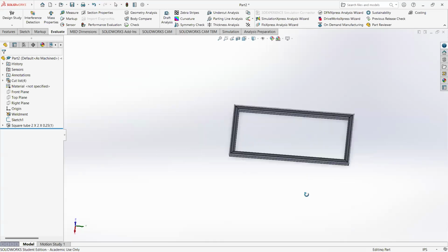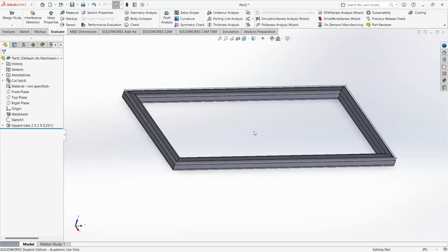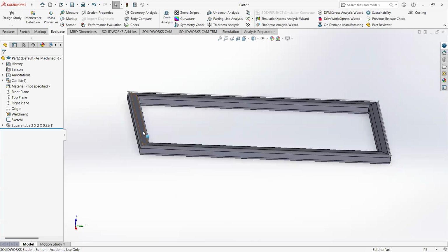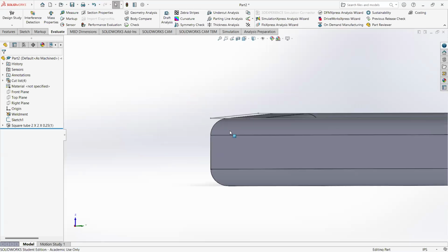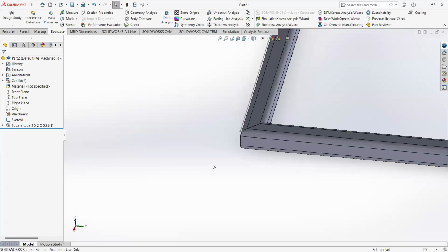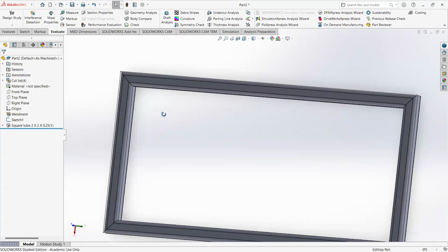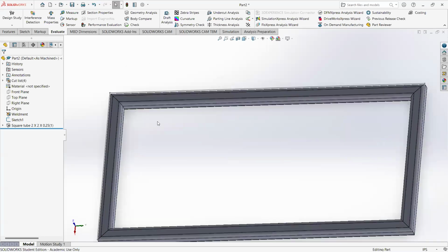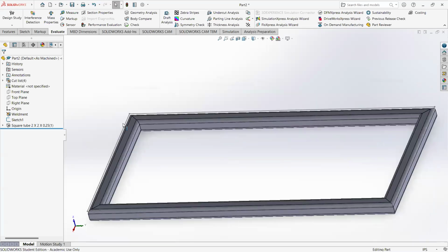Imagine we give this to a welder to fabricate this thing. It's going to be incredibly difficult for him to measure things off of center lines in the middle of a piece of tube steel. So usually I end up relocating to one of these corners out in space. That way, one way or another, my weldment ends up entirely within the dimensions, and then I can create my sketch to true dimensions. I don't have to worry about how thick the tube is, or that I need to add an inch to each end and that kind of thing. So that's one of the key tricks to getting the most out of these weldments.